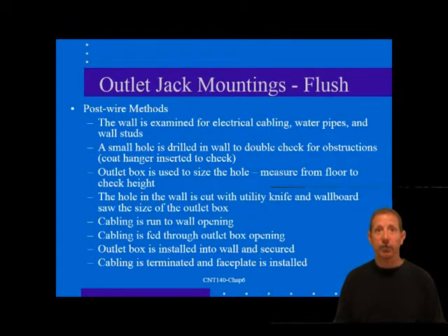The opposite end of the string should be secured to anything above the top plate where it will be visible to the cable installer. After the wall construction is finished, and preferably before the ceiling tiles are in place, the cables are run from the wiring closet to each outlet's pull string, attached and then pulled into the outlet, where they may be terminated. Pull strings and conduit are effective ways to run cable into difficult outlet locations, such as below windows or in columns. The cable may be coiled and secured above a planned outlet location for later pulling into an outlet box or a ring.